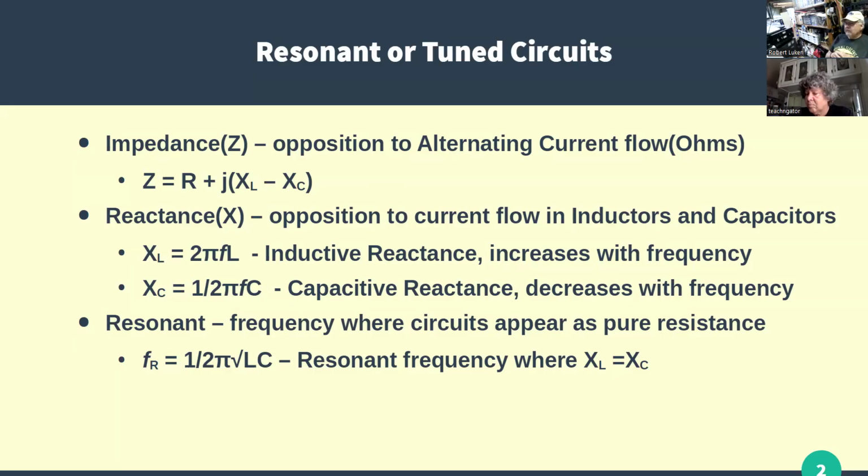So its behavior is in between, whereas an inductor at DC looks like a short. It's just a piece of wire, and it doesn't create much of a magnetic field. At DC, it's a constant field. But at high frequencies, an inductor has a very high impedance, and it becomes essentially an open circuit for very high frequencies. So those two operate just the opposite of one another.